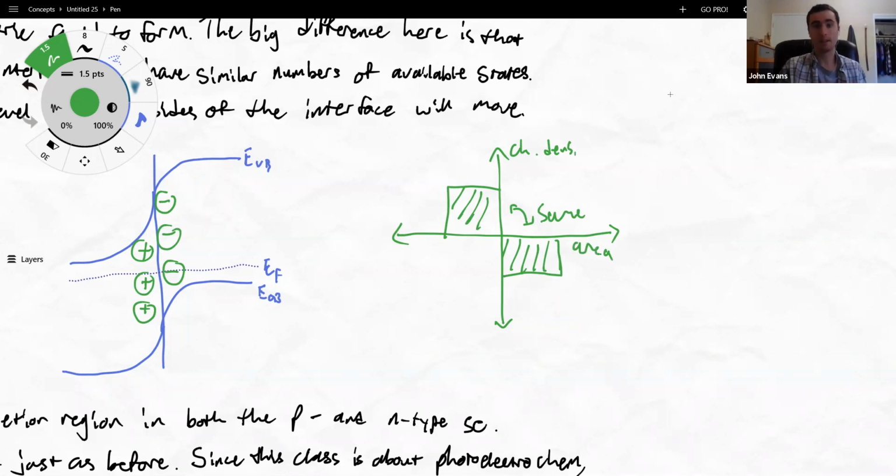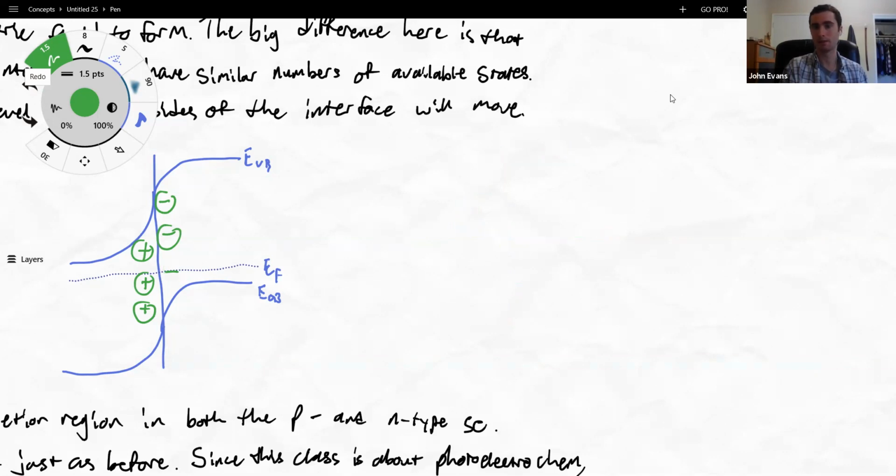So what could happen is, let's say that one of these is more highly doped than the other. So let's say the N type is less highly doped. So the P type, this side, is going to be more doped. You would get a thinner region here. Remember, because it has more states to accept those charges going back and forth. But you should still get the same area in between the two. Again, this works for the regular junctions as well. It's just that that area is so thin as to be ridiculously small. We don't care about it.